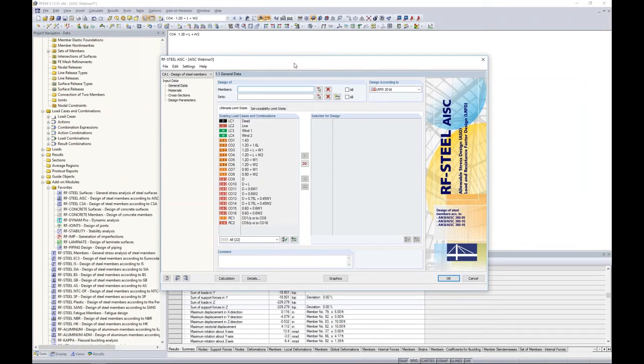All that we're doing is defining a little bit more information that's relevant to the AISC specifically in order to get that unity check from the standard. So what I want to first start off with is I'm going to rename this case. I go to File, Rename Case, and we'll call this one Columns.